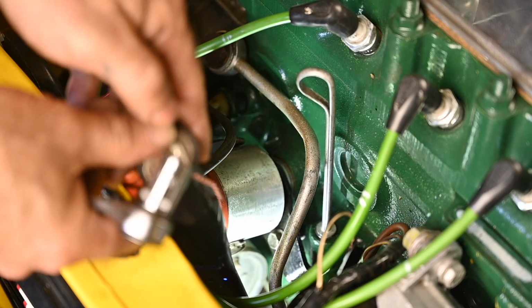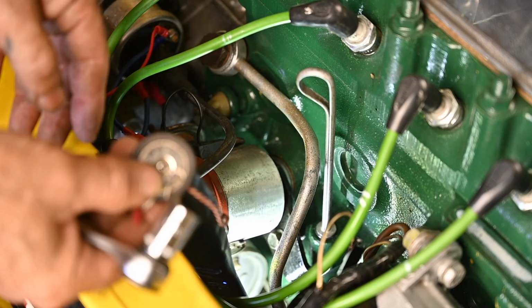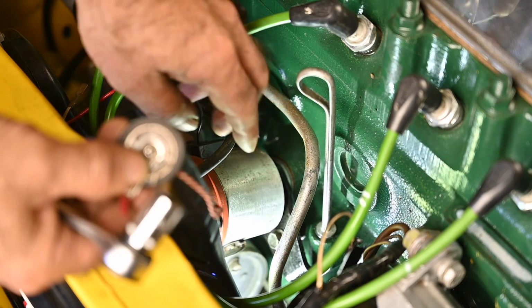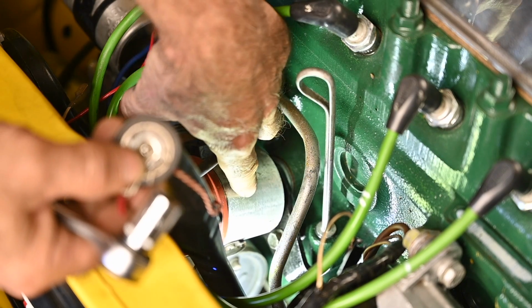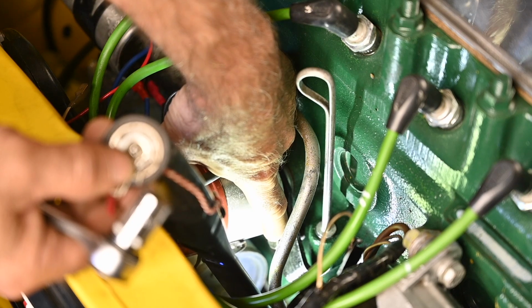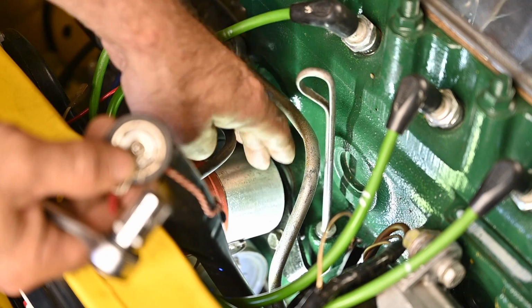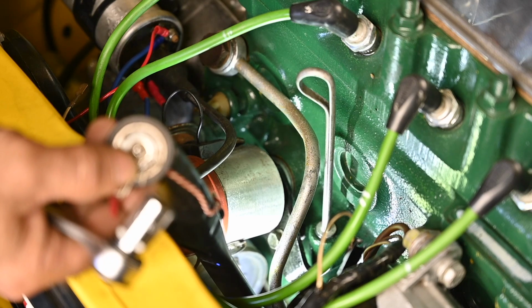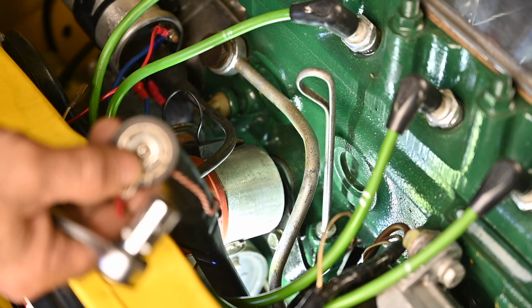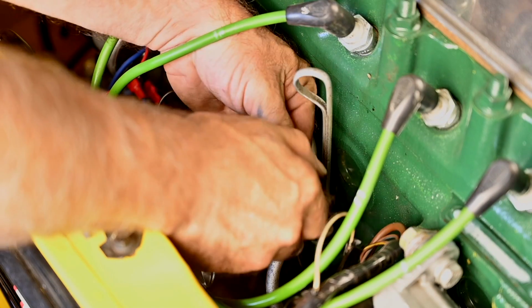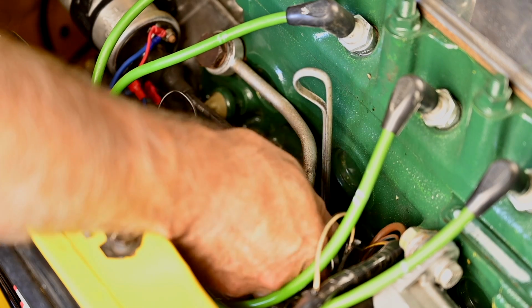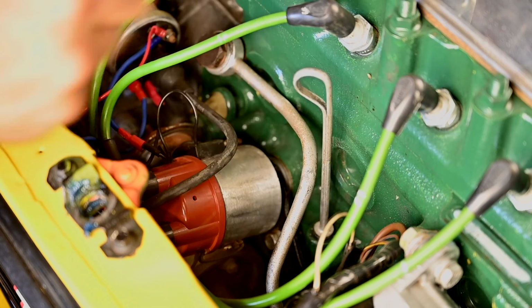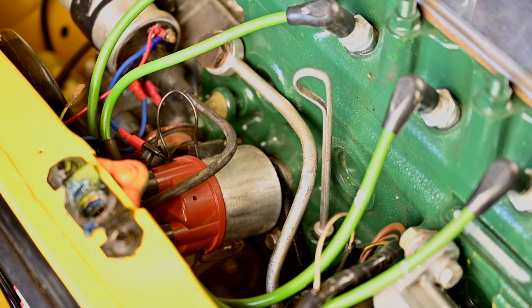And this is going to be a little bit difficult because I don't have a lot of light inside. But over here, that's the clamp that is holding the distributor. So I'm going to loosen that up a little bit, and then I will rotate the distributor to make sure that my timing marks are set to about 10 degrees advance or something like that with my strobe light. Now don't make it too loose either, guys, because that's not good. Loose enough so you can actually rotate the distributor. So that should be loose enough.